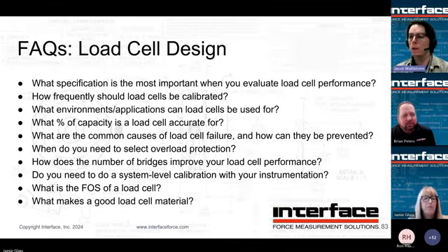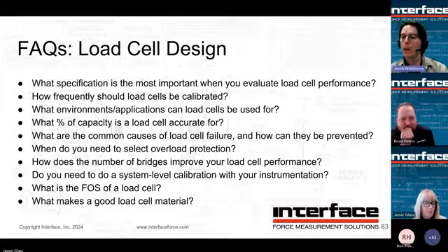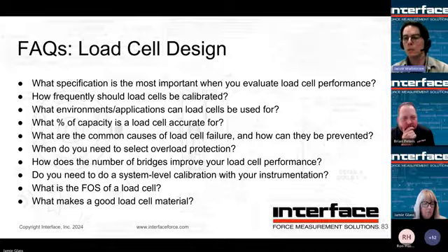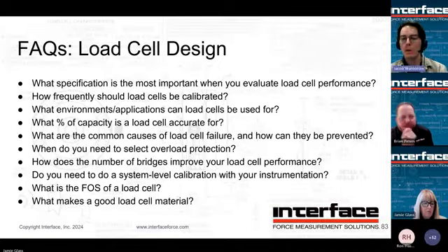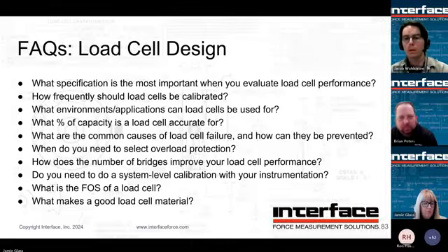Yeah, so if you have a second axial bridge, that won't necessarily improve your performance, but it can give you some redundancy and a clean second signal. However, if you have a multi-axis, right, so you have another axis being measured, that can give you a lot more confidence in your readings, knowing how many other off-axis or moment loads are actually being applied.